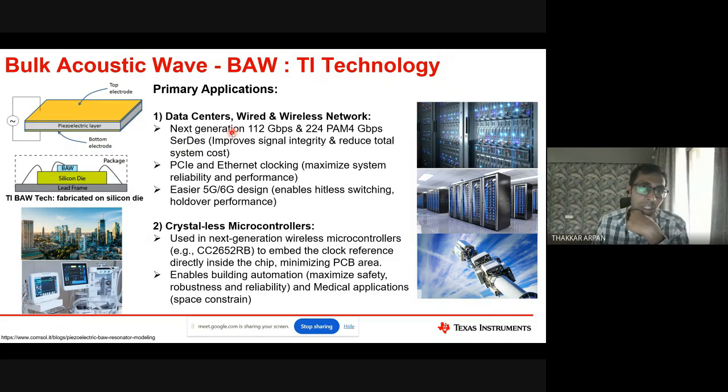If you filter them out, it will just become a sine wave, right? So what I'm trying to say is higher harmonics are not a problem. So this BAW itself can magnetically couple to a different channel, so the 1 gigahertz signal will have a signature of 2 gigahertz itself, right? And 500 meg also will have, but they are its own harmonics, right?